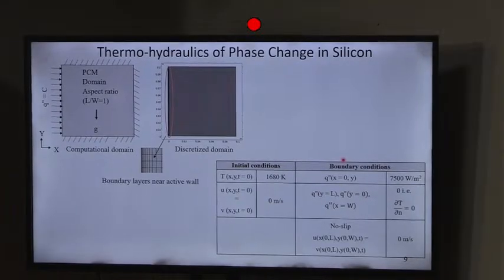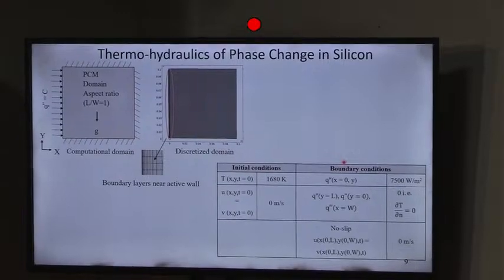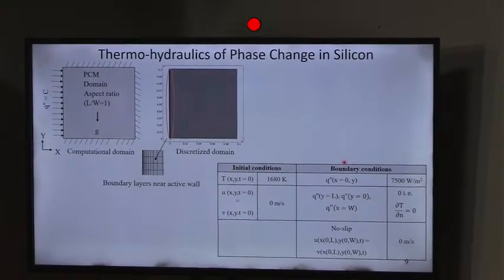There are many boundary conditions you can impose, from more realistic to more idealistic. The ultimate aim is to see at what temperature the sand is getting. Once the sand melts, it goes through this constant temperature latent heat thermal energy storage phenomenon, and that's how you can charge and discharge at such high temperature and get a better second law efficiency thermal battery.